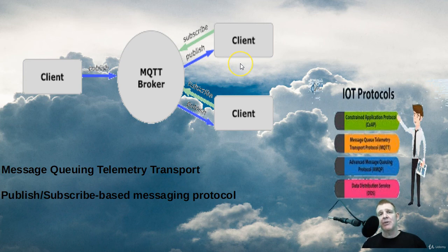That means when we're using MQTT protocol over TCP/IP, we get subscribe and publish. So no matter where you are, like a little node client that's sending sensor data, maybe you only want to publish data from the device and then subscribe in the cloud. And then once it's in the cloud, you can do whatever you want. That process is exactly what we're going to do with AWS IoT. Now, if we want to use shadow service and actually, on AWS IoT, publish in the cloud and subscribe on the device, that will allow us to send data to the device. So we can publish and subscribe using that pub/sub model in both directions with MQTT protocol.